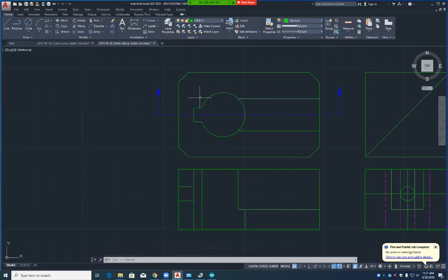Cool. Okay? Now, to hatch this, wherever you cut, if you were to put a knife through there, wherever a knife would touch material, it has to be hatched. But if it doesn't touch it, you don't want hatching there. So the middle of the hole doesn't touch it, does it? The middle of it doesn't, but the sides do. So we want that hatched.